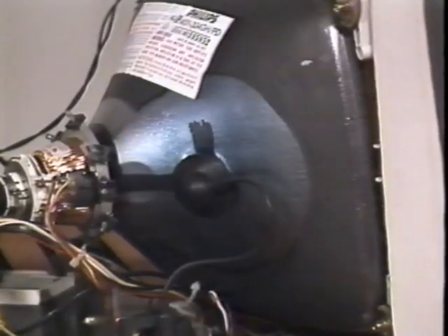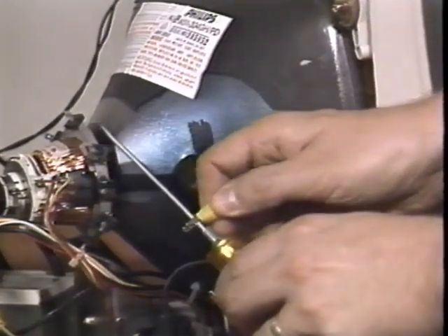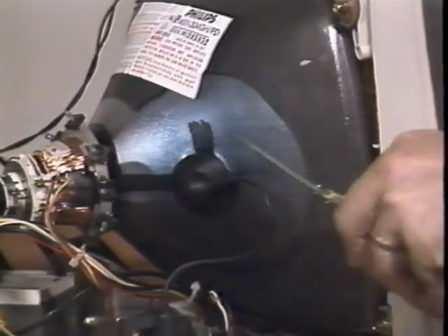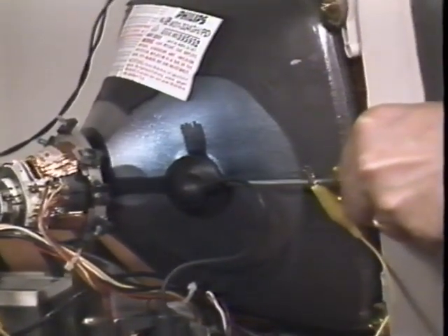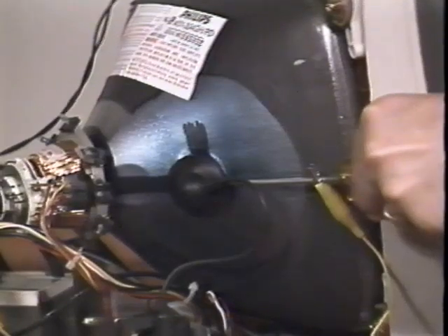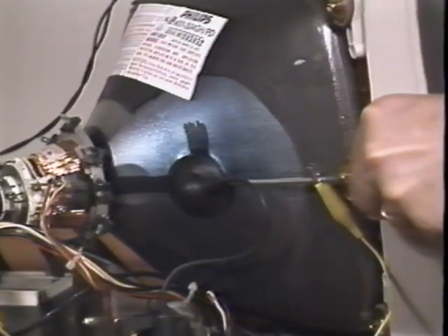Connect the other end of the resistor to an insulated screwdriver and carefully insert the blade under the cup of the anode lead. Be sure that you are not touching the screwdriver blade with any part of your body. Use one hand to handle the screwdriver and place the other hand in your pocket.